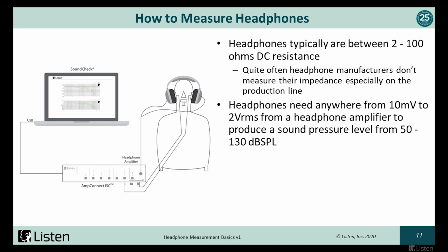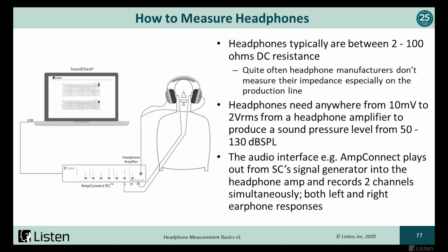Typically, headphones need anywhere from 10 millivolts to 2 volts, depending on the design. They can get quite loud, and this is where you've got to be really careful, because the earphone is right next to your ear canal. The loss due to distance is minimal, so you can get some really high sound pressure levels at the ear and damage your ears if you're not careful.